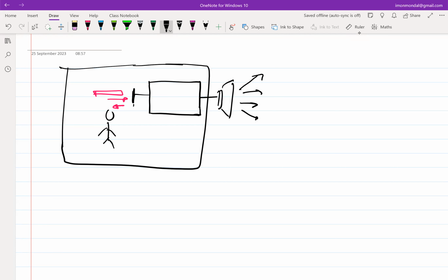So this is what we call an open loop control. This particular scenario that I just described is an open loop control, where you don't have any output that you are observing. You just assume that you know the transfer function. I found out the transfer function 3 days back. If I know that I set the slider to 75% of its maximum, the volume is so much, and I set it there. But let's say that because of changes in weather, or because the music system got damaged or something happened, the volume actually changed, I will not have any information to fix it because I am not observing the output. Okay. So this is the problem of open loop control, right?